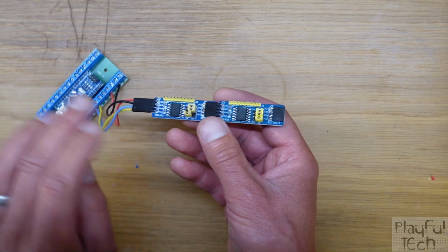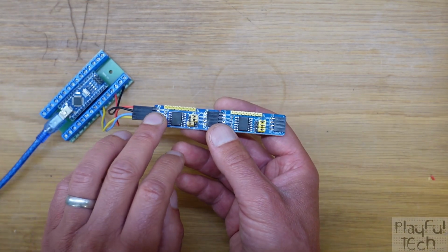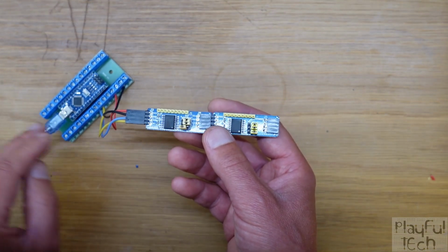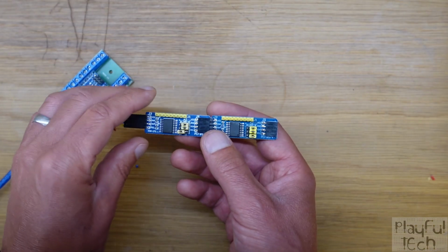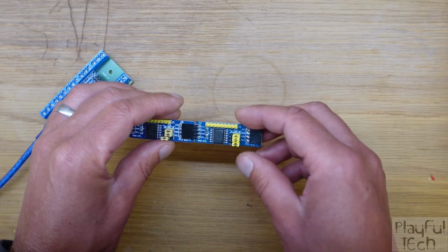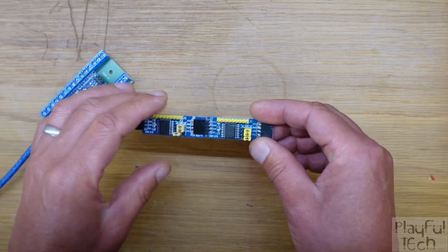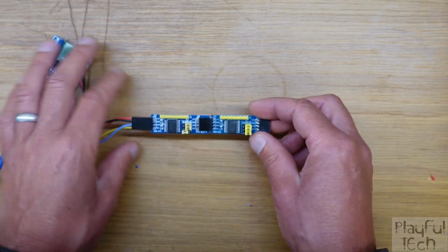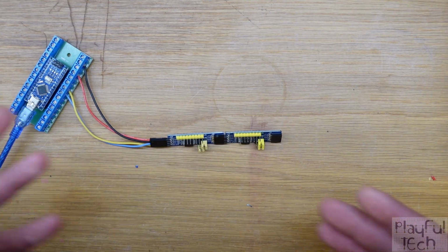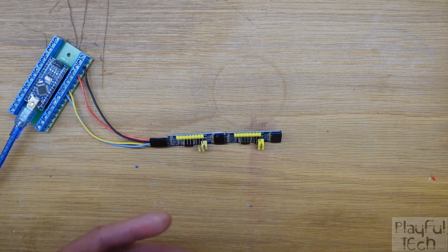You can actually also get a variation of this chip called the PCF8574A, and that has a different range of 8 I2C addresses. So you can also have 8 of those for a total of 128 GPIO pins. So we've got all these available GPIO pins. Let's do something useful with them.